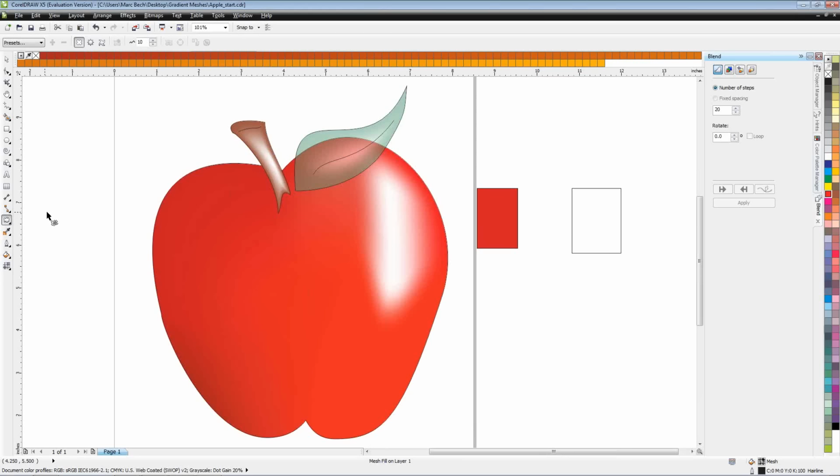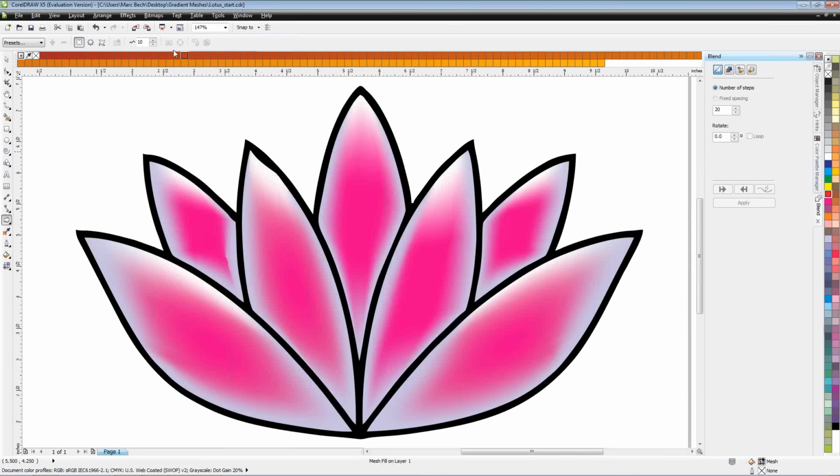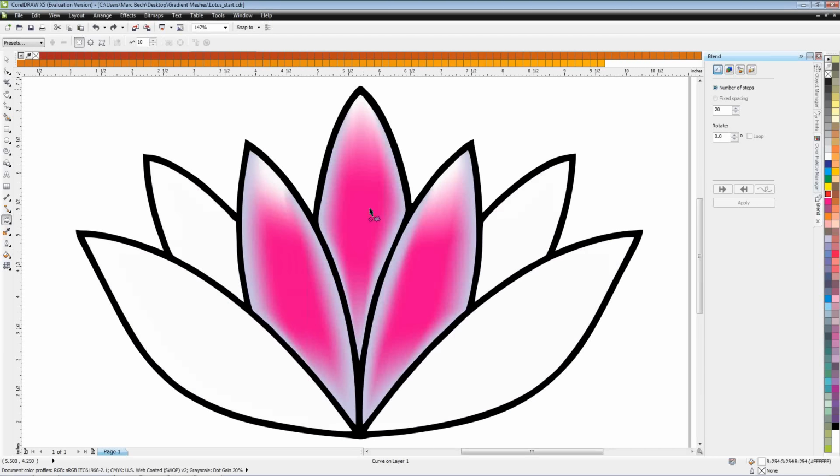advanced in the mesh fill tools. So one of the tips is you can copy mesh properties to multiple objects by using the Ctrl+R key. I'll be darned. Let's give it a try. So I repeat, you can copy mesh properties to multiple objects by using the Control plus R key. Let's see.